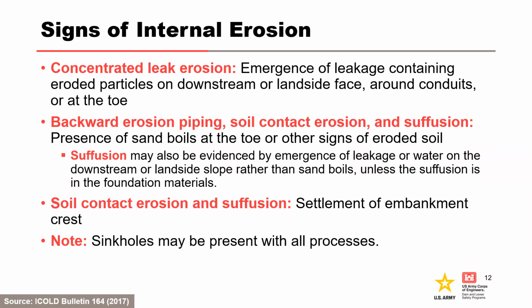The next set of slides will discuss detection. Internal erosion incidents have typically been discovered by visual observation, sometimes by the public. Here are some signs associated with each internal erosion process.